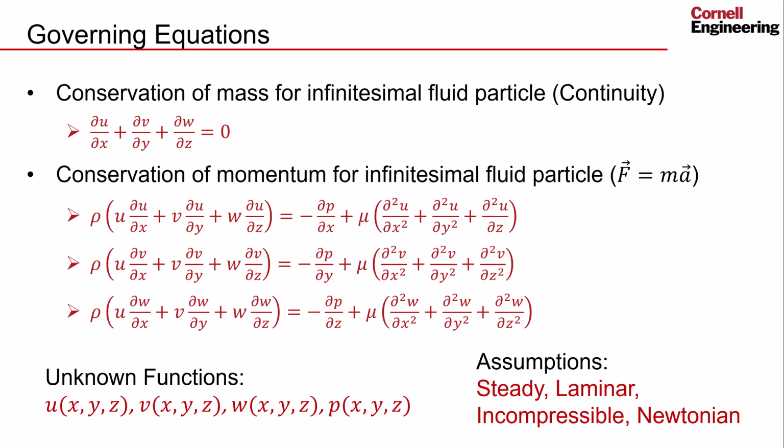Similarly, we will assume that the flow is incompressible, meaning that the density is constant everywhere. Finally, we will assume that the working material behaves as a Newtonian fluid. Note that blood is not strictly a Newtonian fluid, but it will be approximated as such for our model. All of these assumptions are built into the governing equations shown above, and we will ensure that they are correctly provided to the solver.